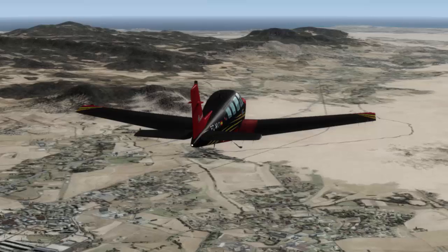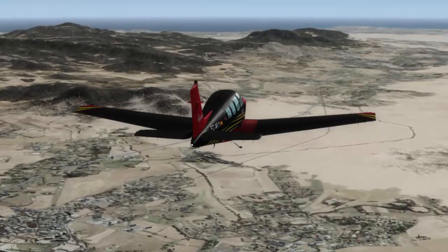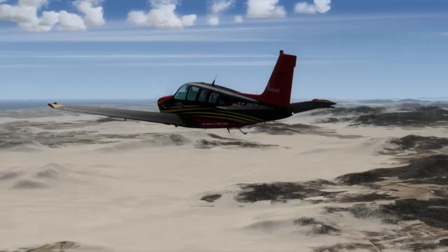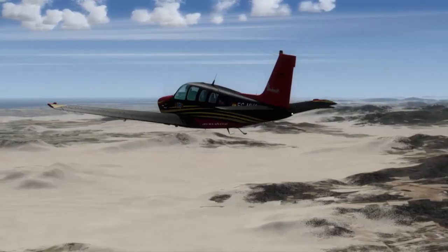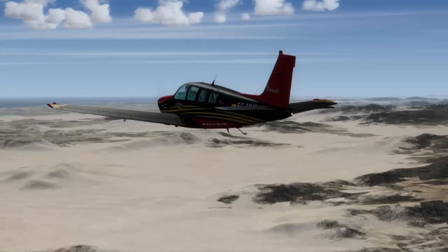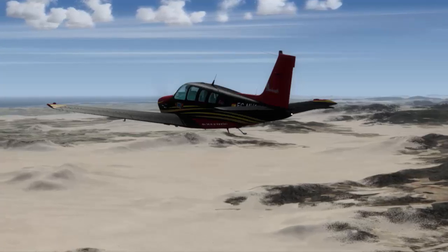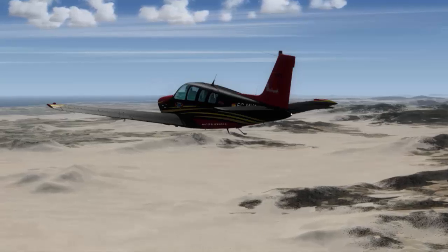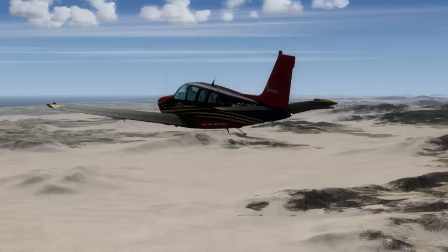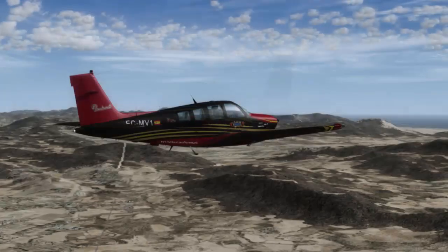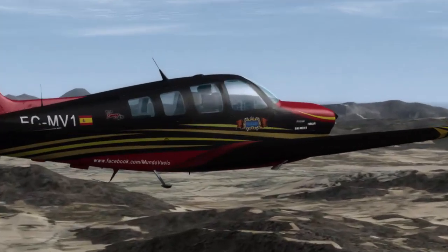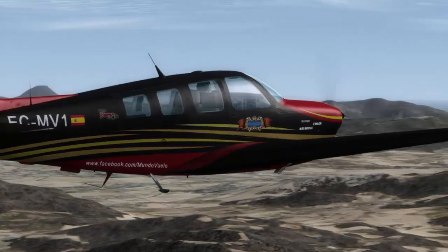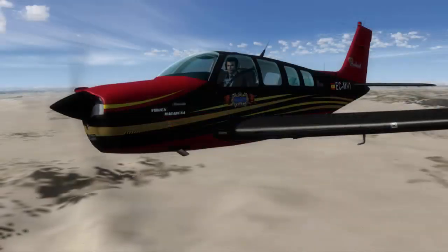And I'm giving you some exterior views, and the exterior views of the aircraft you have there is magic. We are very close to Alicante because we are going to the Alicante VOR DME. We won't follow any radial from this VOR because people could think, well, if you are flying to a VOR, you will follow a radial to get the VOR. No. We are just flying to the geographical coordinate of that VOR, and that is enough, okay? We won't be following, in this particular case, any radial.